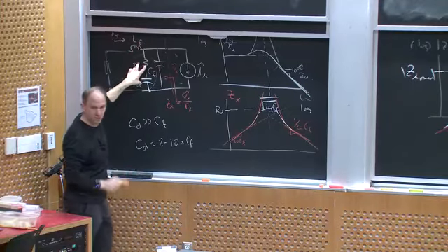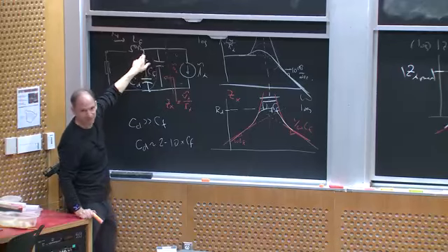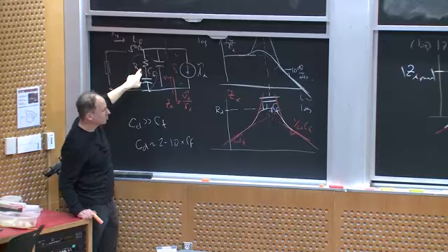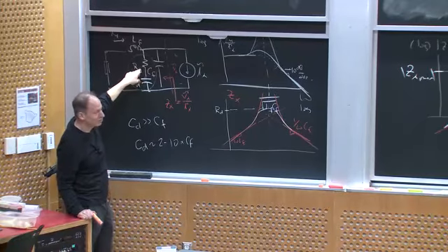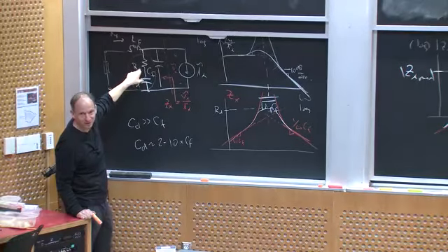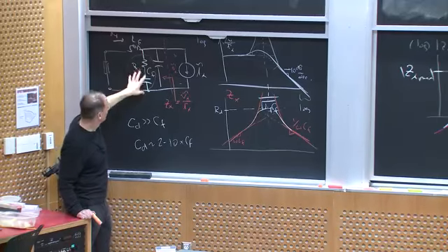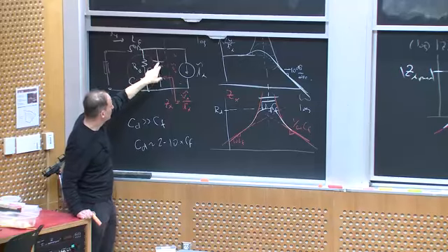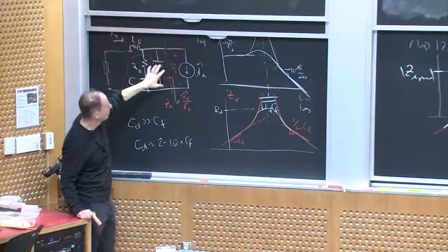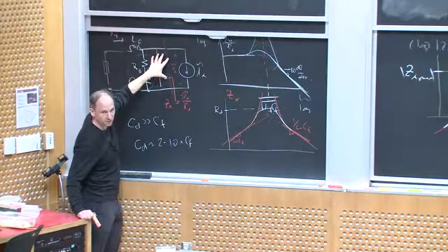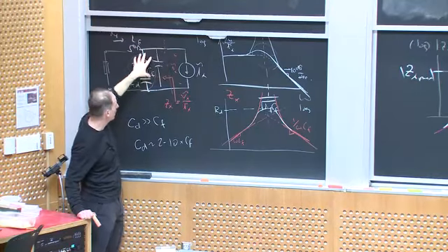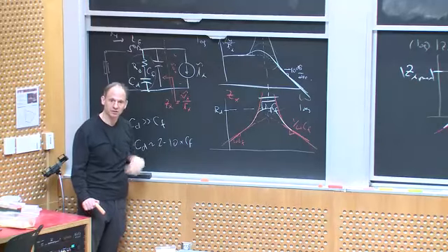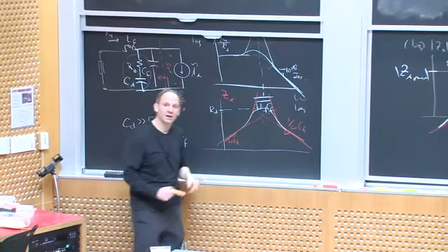So CD doesn't have to be a great capacitor. In fact, if CD had parasitic inductance, I probably don't care that much. If he has parasitic resistance, I still may not care that much because I can use that parasitic resistance as part of my filter damping leg. So this might be, for example, an electrolytic capacitor, whereas this might be a film or ceramic capacitor. So the jobs of these two capacitors are different and the construction of them. And you can get a lot of energy storage in electrolytic, for example, as compared to a ceramic or a film capacitor typically. Okay. Any questions about that?